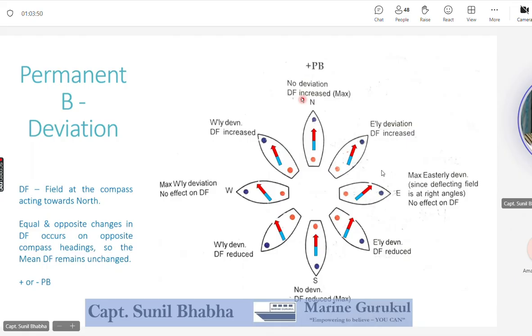So just want to confirm this blue pole and the red pole, are they HSI only? Horizontal soft iron? No, beta, these are permanent poles. So this is because of the permanent magnetism of the ship. So soft iron is not involved here. Okay, sir, permanent poles. That's correct. Horizontal soft iron will come when we go to coefficient delta.